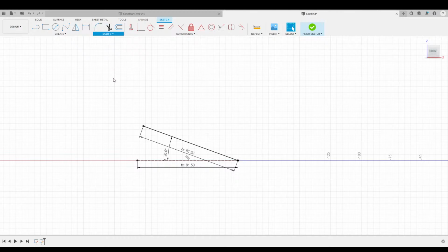So to do that, we're gonna add some more parameters. One of those is gonna be called track height, and track height is going to be 23.5. Okay, and then we have different thicknesses for our walls on either the inside or the outside. And so I had some naming conventions that were kind of mixed up a little bit. Track outer wall thickness, track middle wall thickness. So we're going to have track outer wall thickness, which I believe is 2.5 or 2.25.